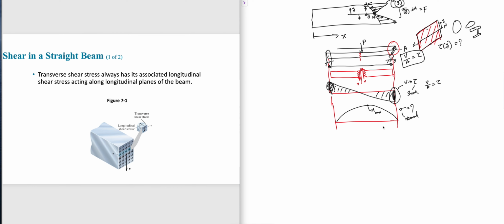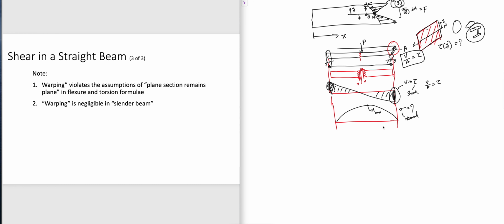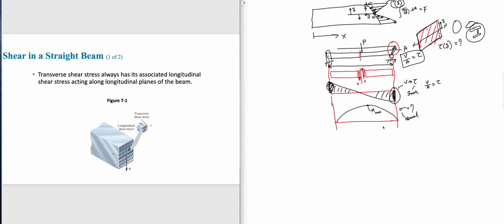If I were to give something in the exam, I would prefer giving you an I, because the majority of building materials have an I cross section. Look at railway tracks. A railway track cross section, on which the train wheels are placed, almost looks like an I. The I is a pretty important cross section. So for an I cross section, what is the shear stress at this point? We need to know the shear stress at each and every point so that we can come up with a proper shape, proper material.